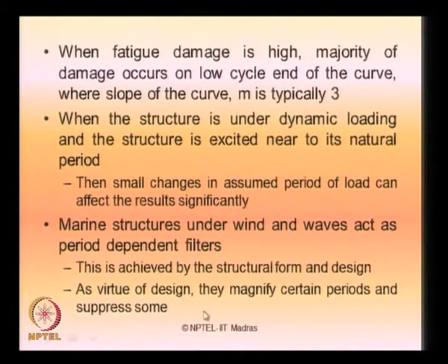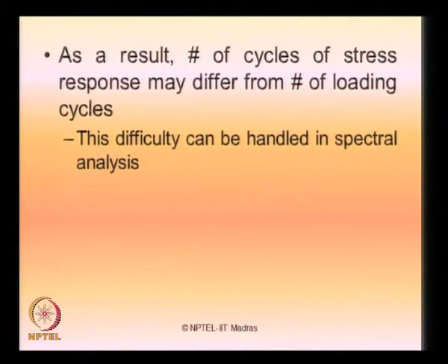As a virtue of the design, they magnify certain periods and suppress some of them. Okay. This is essentially achieved by the structural form and design that you follow in marine structures. As a result, the number of cycles of stress response may differ from the number of loading cycles. That is very important, because you are suppressing the loading on certain frequency domains or certain period domains.